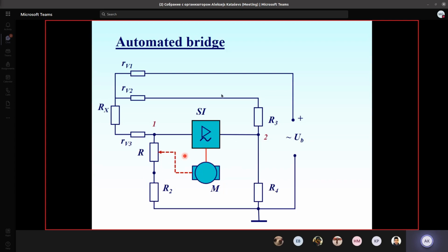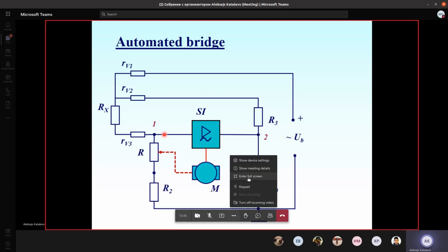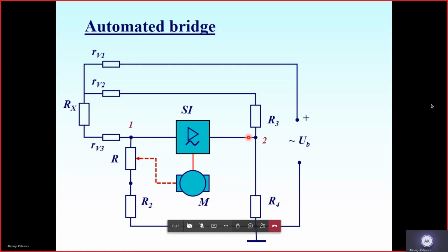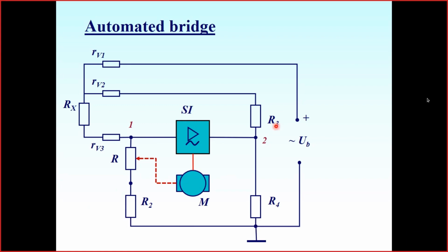to convert the difference in voltage in the unbalanced bridge into the control signal for the motor. So it may be, in the analog case, just the amp directly controlling the motor driver, which in turn drives the motor.